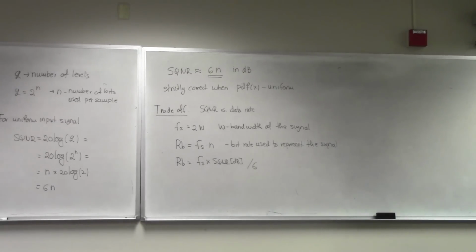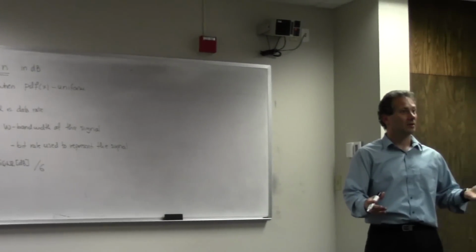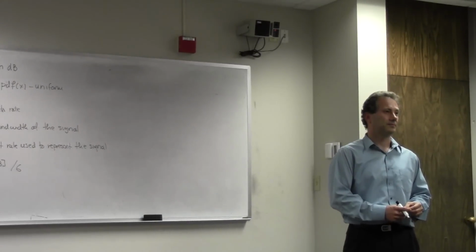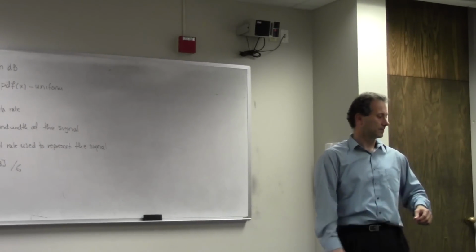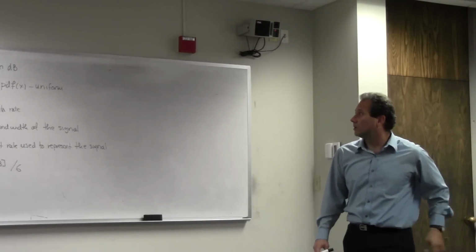All right. So how many quantizations do we have actually in the real world? Two. One is in time and the other one is the magnitude, right? You quantize in time by sampling. You quantize in magnitude by doing quantization. Whenever you have analog circuit design, usually we have quantization in the ADC, analog to digital.